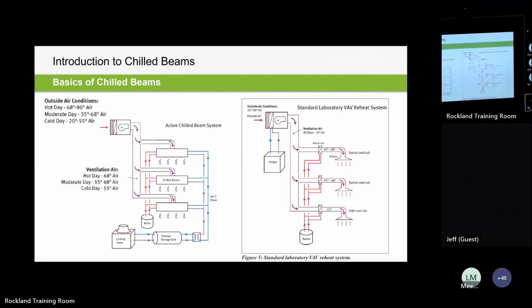Right. So chilled beams suit the more constant volume type of lab, rather than one where the exhaust changes constantly. You could put a Venturi valve upstream of the chilled beam as well, so it's fast acting and operates with that sash velocity.